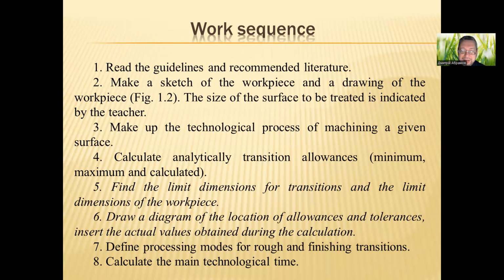Calculate analytically the transition allowances: minimum, maximum, and calculated. Find the limit dimensions for transitions and the limit dimensions of the workpiece. Draw a diagram of the location of allowances and tolerances.